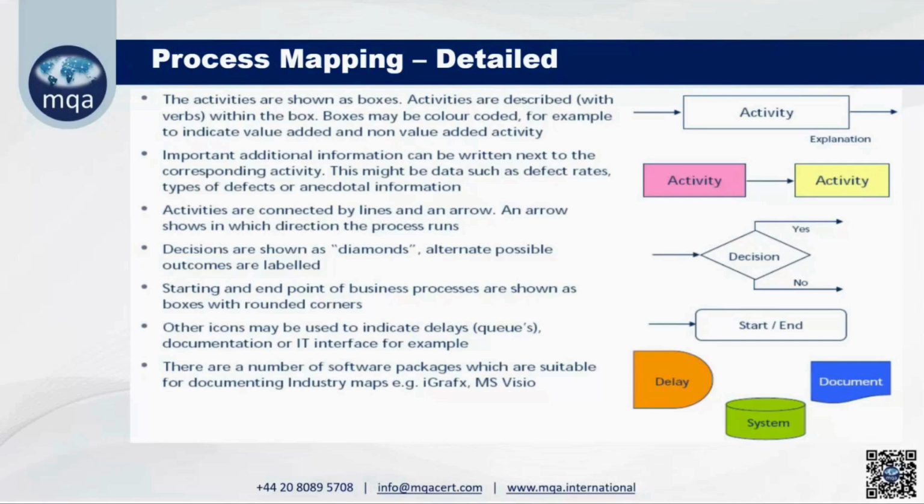If the material is okay, we go to the next process. If the material is not okay, we reject the material, send it back to the supplier, and take supplier corrective action at the supplier end. After the raw material is okay, it goes to the initial first process. The first machine does some process, then the second machine, then the third machine, then it goes for final inspection. Even at each machine there will be inspection stages to qualify whether the machine output is right or wrong, meaning okay or not okay.